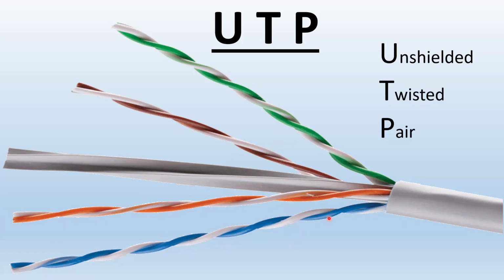So even if you have one twisted pair, and there would be another twisted pair that's twisted at the same rate, they could align physically and the coupling would take place. But no. We're twisting those pairs at different rates. So whichever way they're positioned lengthwise, they're not going to synchronize physically, and thus they're not going to have the magnetic or electromagnetic coupling from one pair to another.